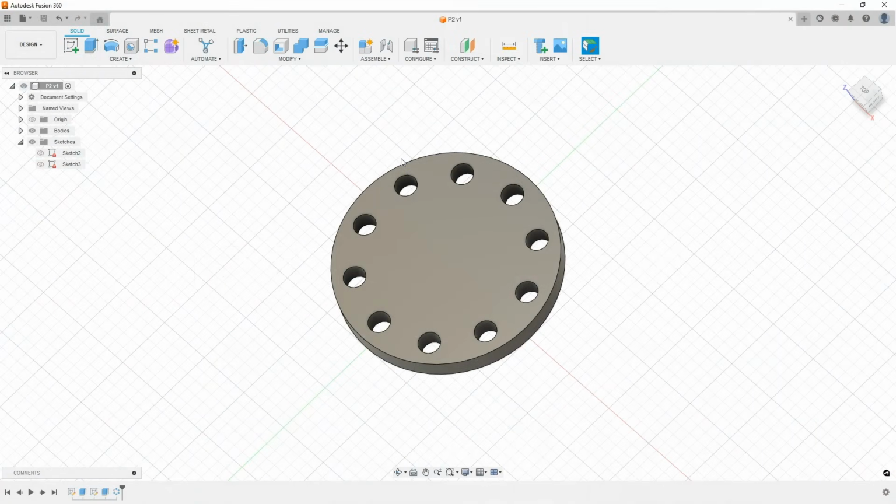In this lesson you will learn how to add fillets and chamfers. If you do not have this project, open this project, and to add a fillet or chamfers to an edge there are a few ways to do it, and you can first select the edges that you want to round or chamfer and then select the command, or you can first select the command and then select the edges. First, let's add fillet, and with the Ctrl key pressed, select the edges to be rounded.